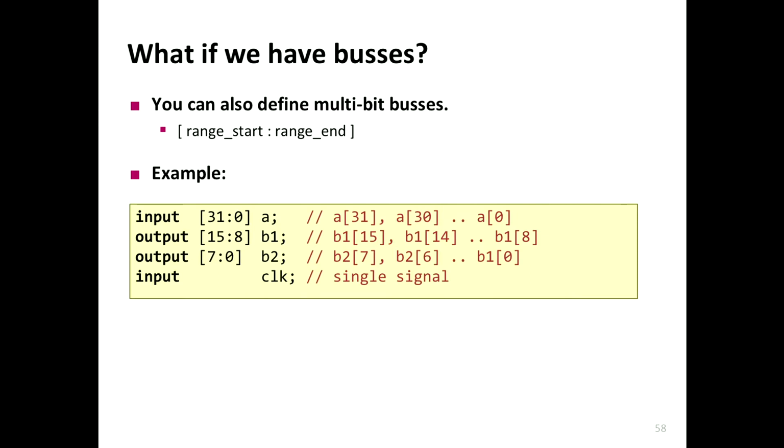But if you say big endian, then you have to read it the other way around. So this becomes your MSB, which basically means you will read 1101, starting from here. And this is big endian format, which means this is going to be 13. So you see the difference. It's good practice to always follow one particular way of telling the system. It doesn't matter when you are the only one designing the whole system.